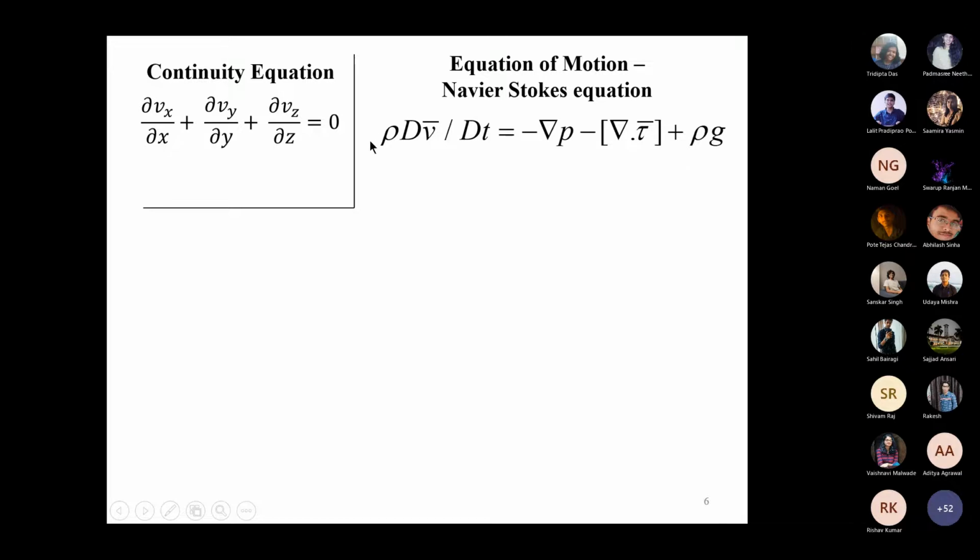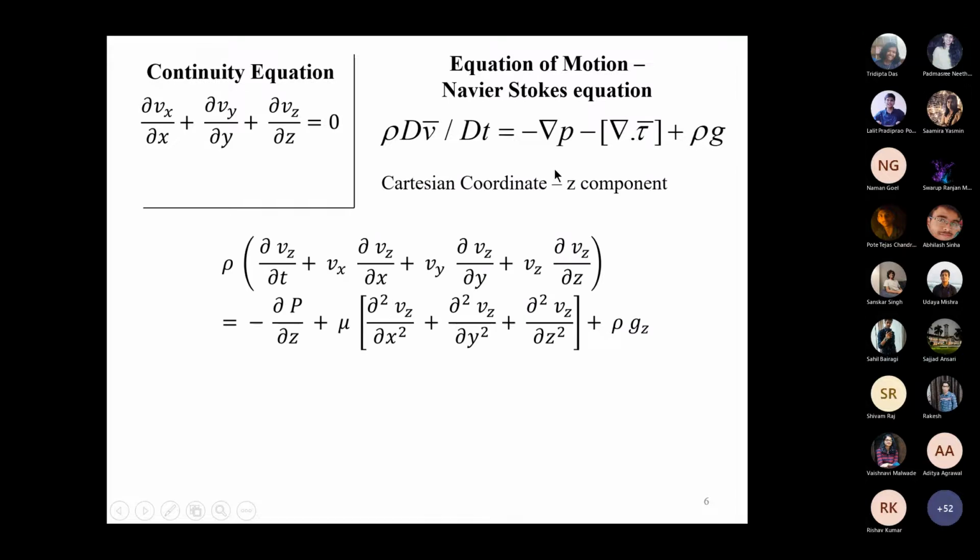So in its present form, the way I have written it, Navier-Stokes equation is nothing but Newton's second law for an open system, where the fluid is allowed to enter and leave the system with a difference in pressure, could be a body force acting in the direction or in the opposite direction of the flow, which would be governed by the sign of this vector.